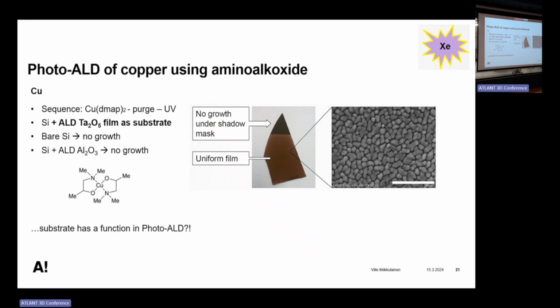You have an adiabatic effect locally. You don't have photo dissociation of your precursor molecules, but you locally bring the substrate into the ALD window with the laser, and the rest of the substrate remains below it, and you have no deposition. Can you comment on that?